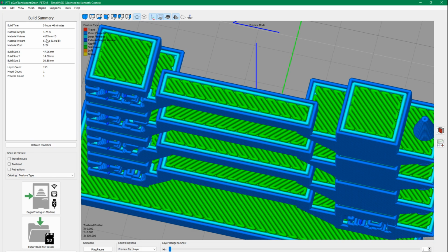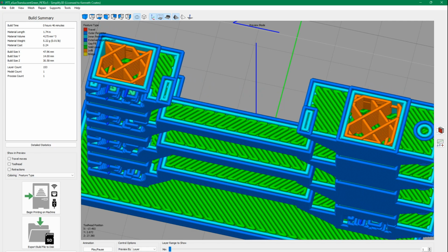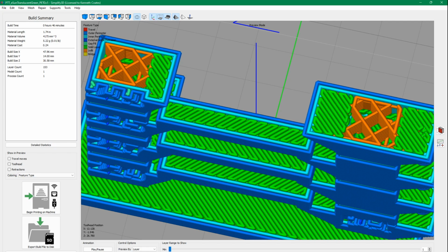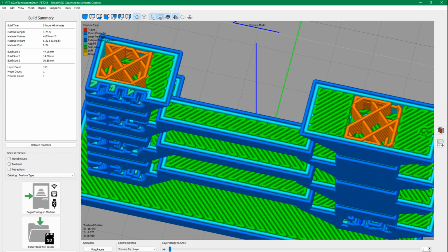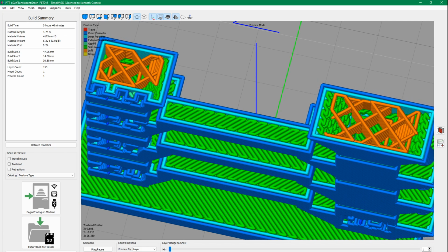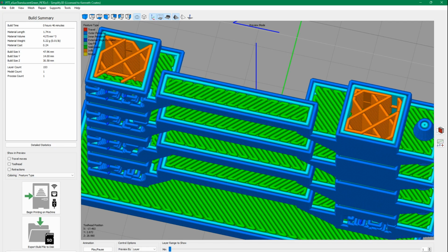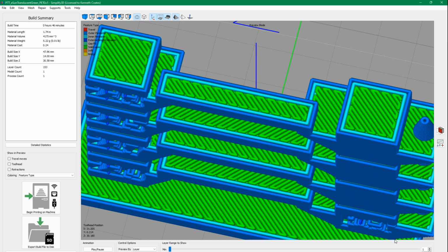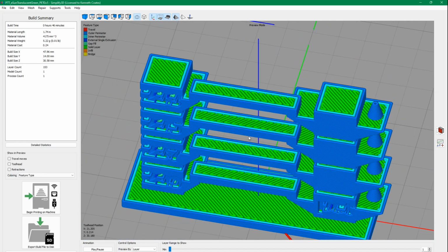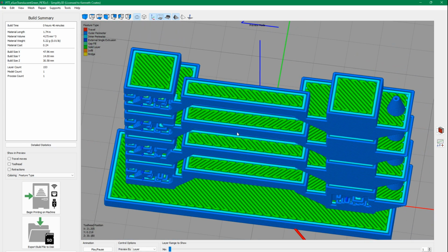Now it says it's actually going to take more material. It's possible because of some of the other slicing things, like when it gets close to a surface, it might put in extra support. It's hard to see it doing that exactly, but when it gets close to a surface, and you have 20% infill, it's supposed to go to 50%. So that's probably a little bit more material there. So for most models, you may turn that off, because I don't think I really need that. Unless I have some tricky printing, I may end up turning that off.